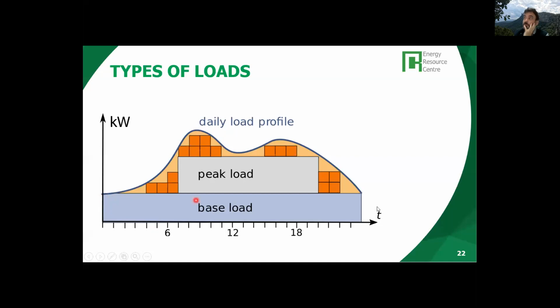And we can also typically observe a base load, a power consumption level that is kept fixed, constant throughout the entire day. Here we can see the horizontal axis of time: the hours in the day, from the start of the day, midnight, 6 a.m., noon, 6 p.m., and midnight again. So understanding the power consumption levels for the base load would typically be the reference to design the battery system, for instance.